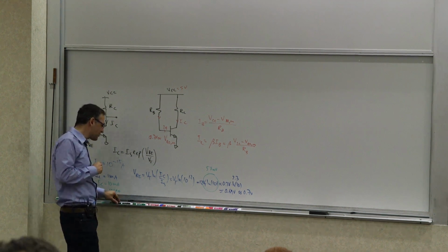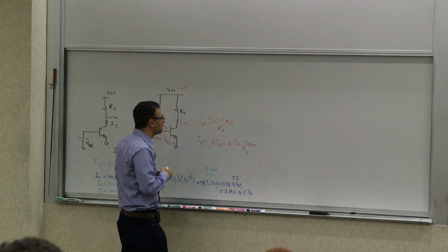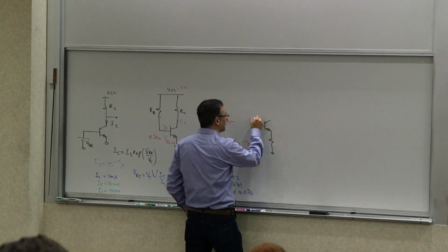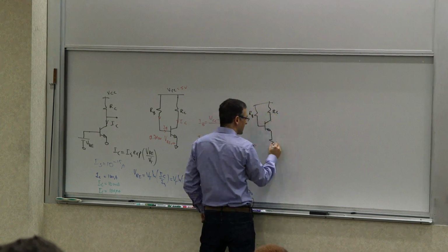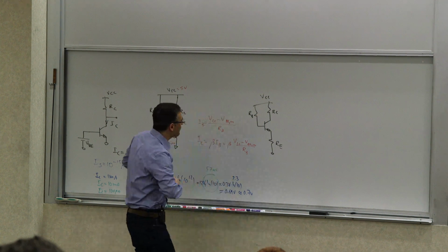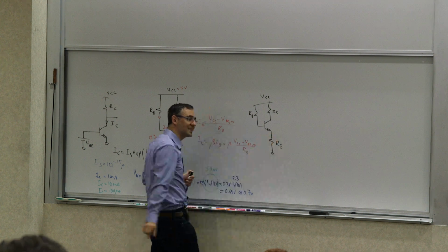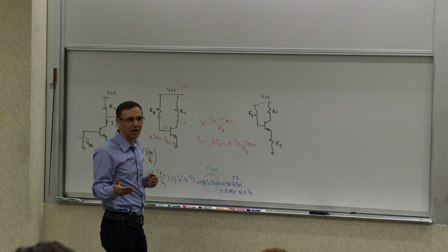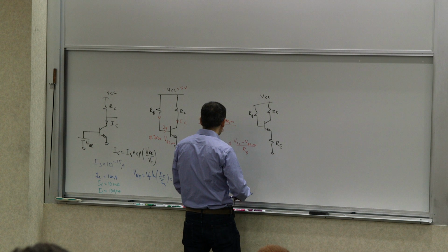I want something that actually takes this voltage and divides it across other things, right? So one way to do that is to basically introduce a resistor in the emitter. So if you take this thing, and you have VCC, now what happens is that this voltage is divided between this and that, but this is mostly carrying IC. I mean, it's IC plus IB. It's IE, but it's close to IC, right? It's IC over alpha.